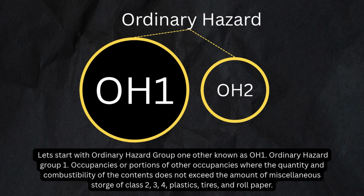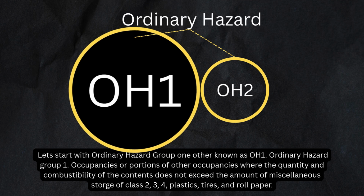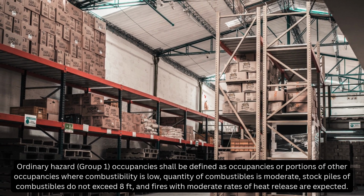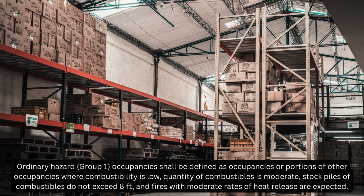Occupancies or portions of other occupancies where the quantity and combustibility of the contents does not exceed the amount of miscellaneous storage of class 2, 3, 4, plastics, tires, and roll paper. Ordinary hazard group 1 occupancies shall be defined as occupancies or portions of other occupancies where combustibility is low, quantity of combustibles is moderate, stockpiles of combustibles do not exceed 8 feet, and fires with moderate rates of heat release are expected.